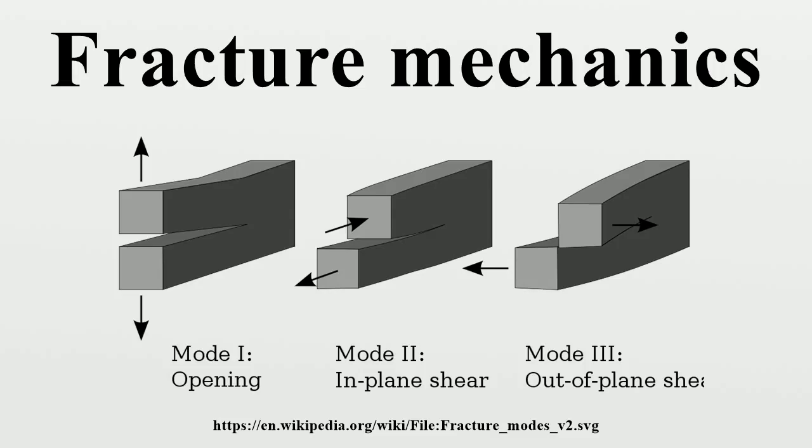Most laboratory measurements of CTOD have been made on edge-cracked specimens loaded in three-point bending. Early experiments used a flat paddle-shaped gauge that was inserted into the crack. As the crack opened, the paddle gauge rotated, and an electronic signal was sent to an XY plotter. This method was inaccurate, however, because it was difficult to reach the crack tip with the paddle gauge. Today, the displacement V at the crack mouth is measured, and the CTOD is inferred by assuming the specimen halves are rigid and rotate about a hinge point.